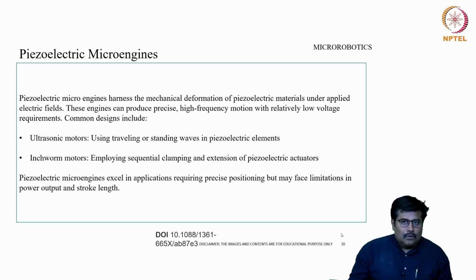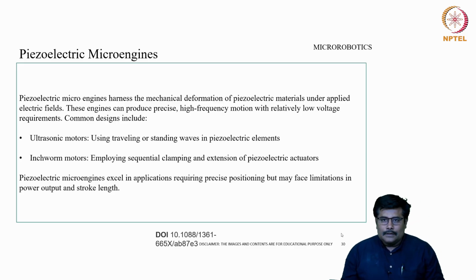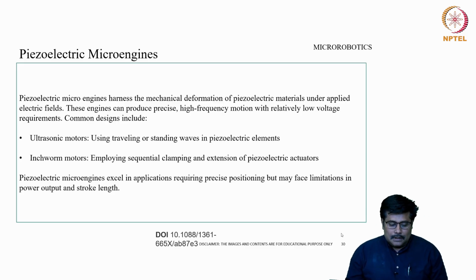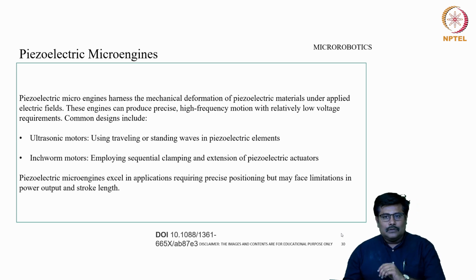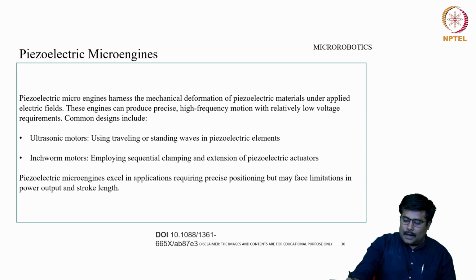Some of the common designs include the ultrasonic motor and the inchworm motor. Ultrasonic motors use traveling or standing waves in piezoelectric elements. However, the inchworm employs a sequential clamping and extension of a piezoelectric actuator.